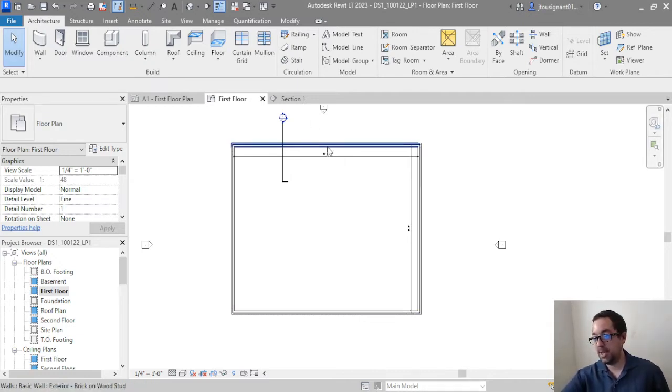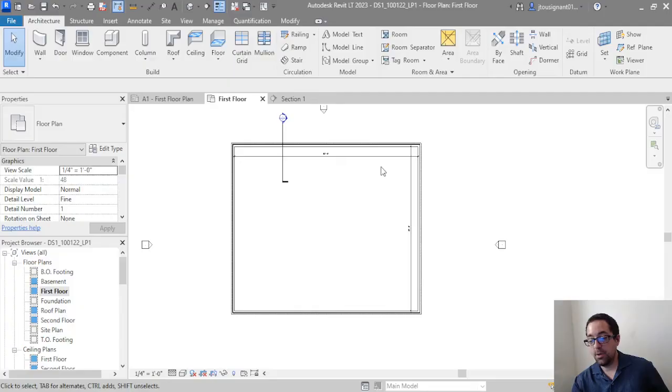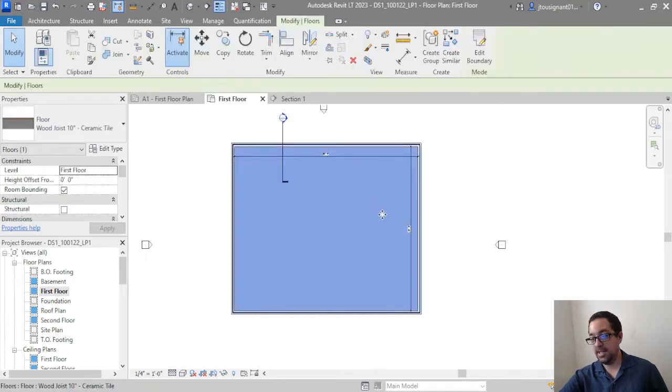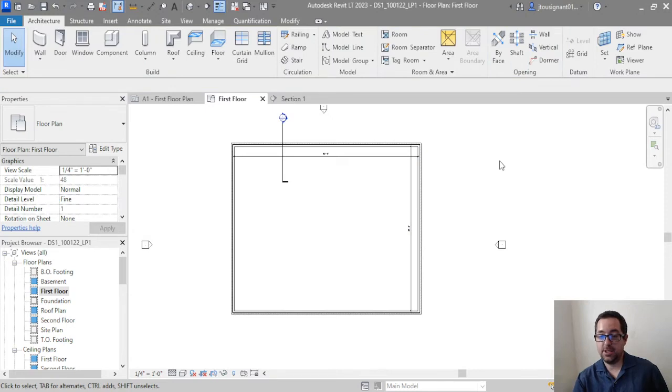If I'm picking a bunch of walls, I might want to have this off because I'm not wanting to select faces. I'm going to make sure that the wall is automatically snapping to the walls that I'm wanting. But if I'm wanting to select faces like windows or floors or doors or something that might not have a hatch on it, it is helpful to know that you can turn that on, and that's going to help you select faces without hatches.